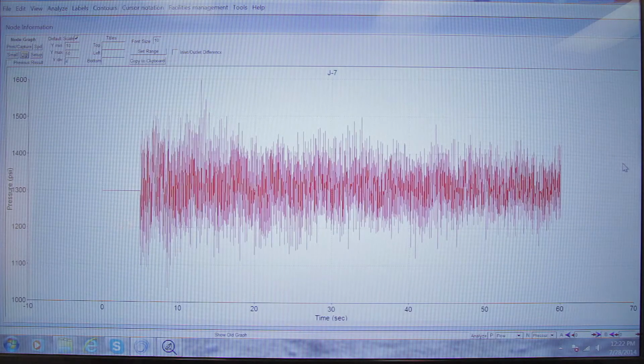Okay, so here's the shock wave that occurred in my low pressure piping. In this case, we're exceeding the pressure rating of that piping, getting up to 1600 psi. And again, this is what happened when the injection pump tripped. That shock wave is coming back into our piping. Again, this is a higher pressure scenario than what we were looking at before. But you can see how this could damage the piping and the injection equipment if this shock wave is allowed to enter into our low pressure piping.